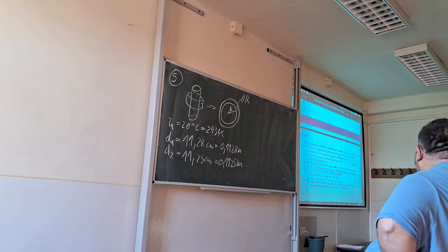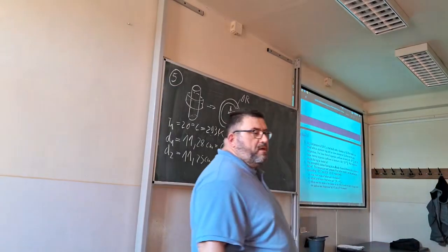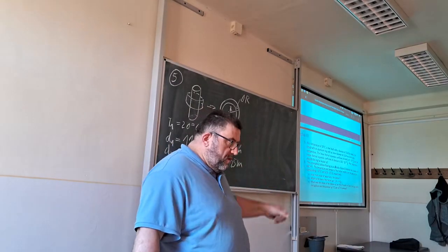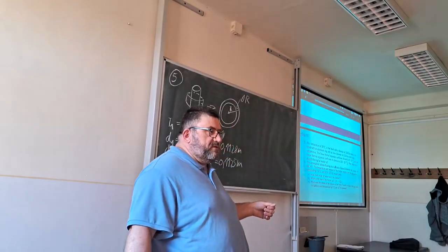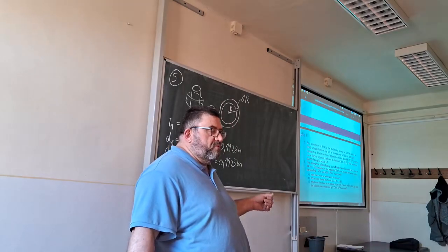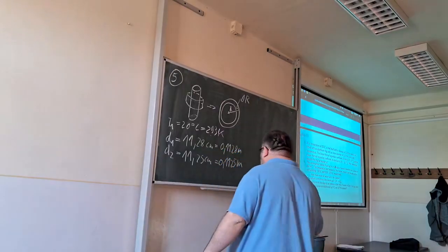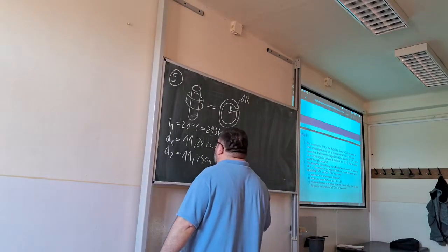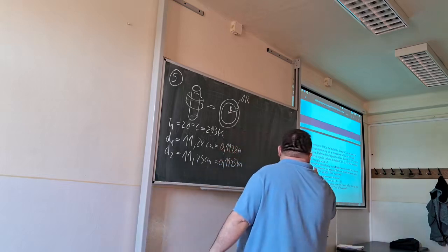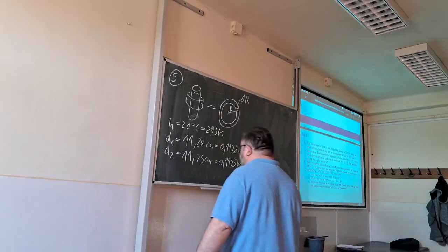Sweet. There are two ways to do this. The first way is to take the ring, heat it, and then hammer it onto the shaft. That's the simplest way. The other way, which is more difficult, is to heat both of them. I will start with the first one because that's the simplest, and then we can do it again next time if it's not what they thought. So here I need, how much time do I have? 8 minutes. Okay.